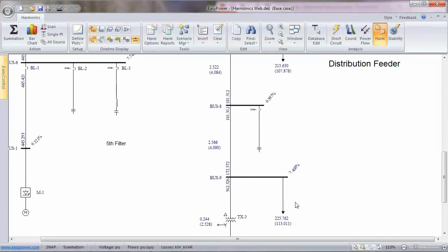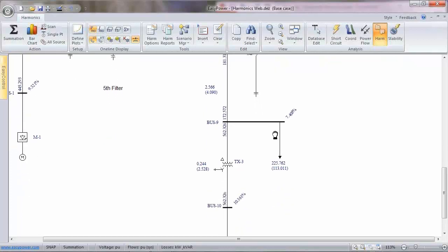So again, it's your system. It's going to respond depending on what you have in it, the amount of capacitance balancing with the amount of inductance in the system. We'll simulate it at each of the harmonics. We'll apply the weighting factors for you, and then you can begin mitigating efforts, placing capacitance in locations, trying to absorb some of the higher frequencies, maybe even putting harmonic filters on. For distribution feeders, I've discovered harmonic filters typically don't work well. Just a carefully placed capacitor bank is one of the best alternatives that I've seen.